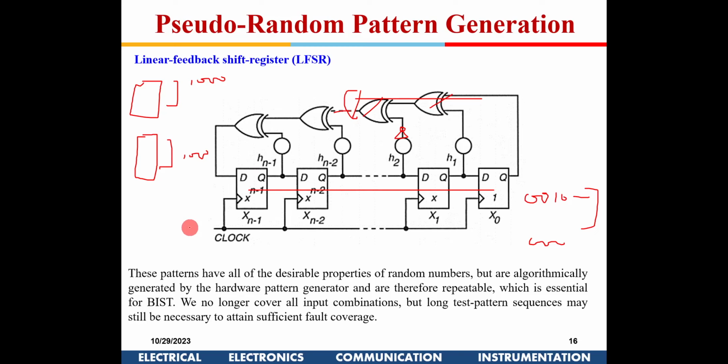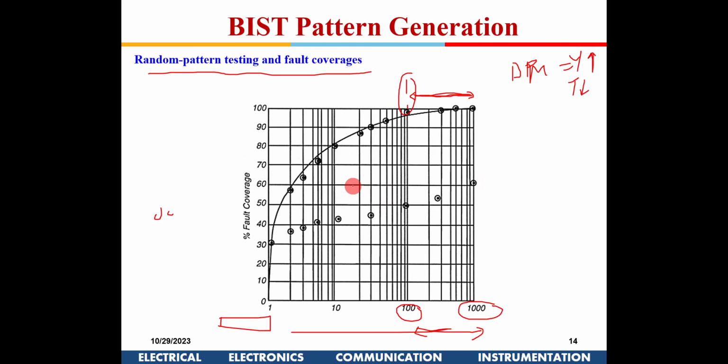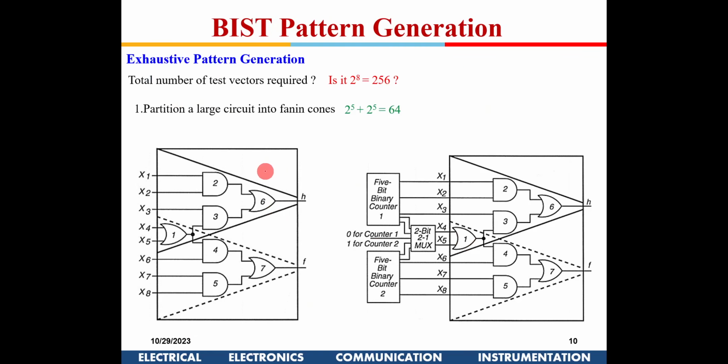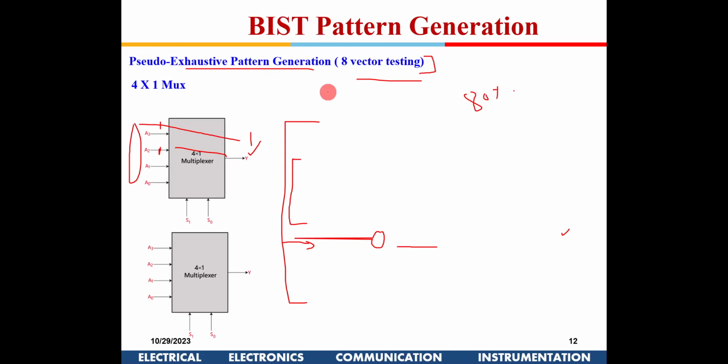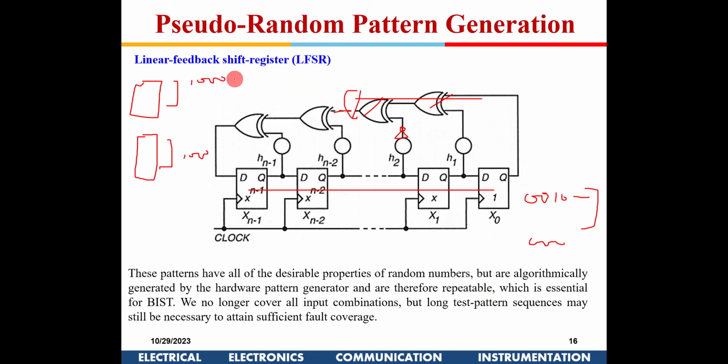Generally, what we saw here takes care of different LFSRs for different small neighboring gates, but in this we have one central LFSR generating various test patterns for various circuits. It is not that you have one LFSR which will generate some random pattern applied to every circuit. That is not the case. You can customize this particular circuit by feeding the initial data accordingly and generate the kind of set of patterns.